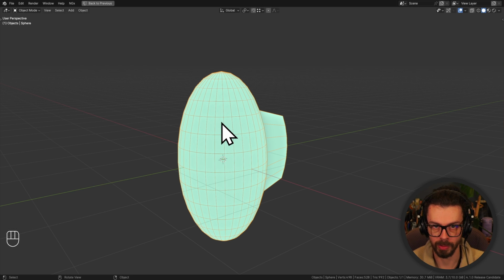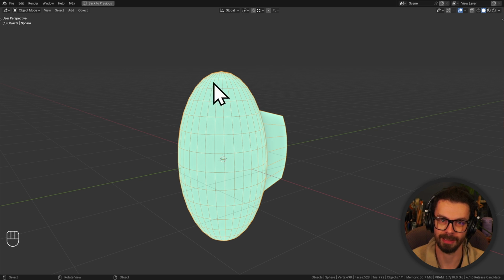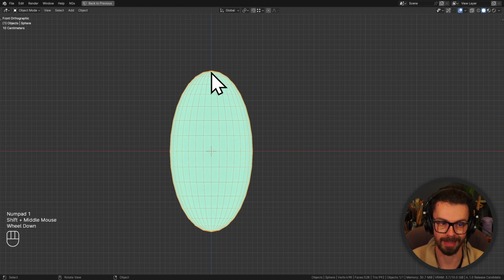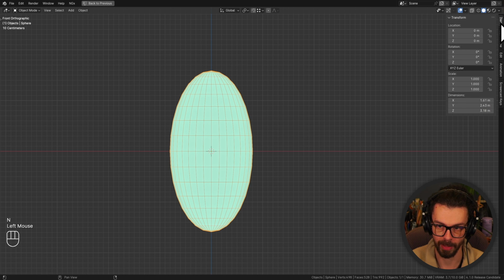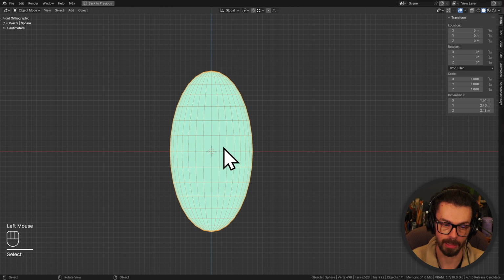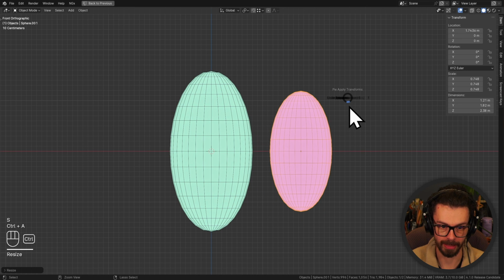Something like this when you're making an object for building a tool. Sure, it's useful to do the actual objects that you're going to be using, but it's also important to learn how to make debug objects and the things that you're going to be looking for. So for us to ensure that we have the right control, I want to make sure that this is an atypical size. If we have a look at our item size, this is 3.18 meters. It's just random dimensions, basically. That's much more useful than having something which is exactly 1 meter across or 2 meters across, because that is going to potentially cover up errors in your system. Equally, let's make a second one. I'll make it a different size.